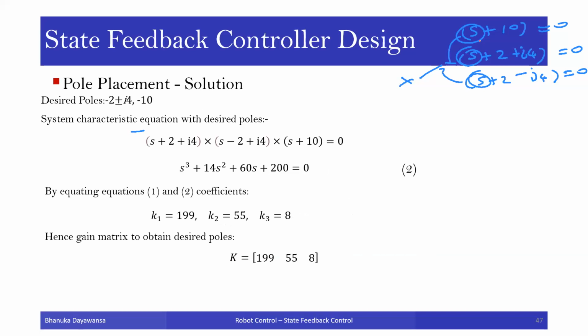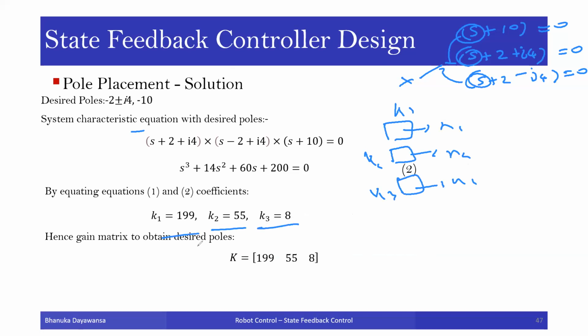So basically, it means there are 3 state variables, x1, x2, x3. If we give these 3 Ks, K1, K2, K3, to the system, similar to PID tuning, right? Then the system will obtain a stable trajectory of the robot, instead of the unstable one. You give these 3 values, the system becomes stable. Okay? It's very simple. It's not very complicated, right?